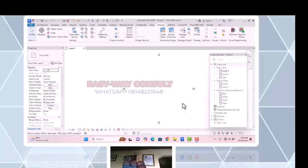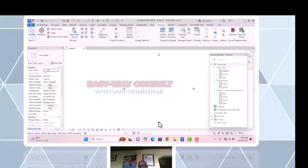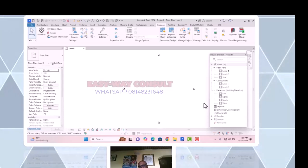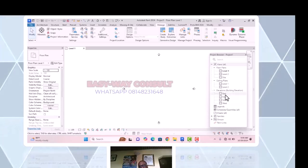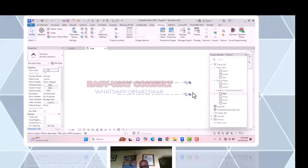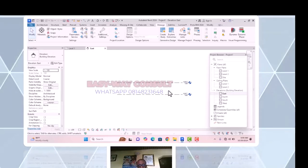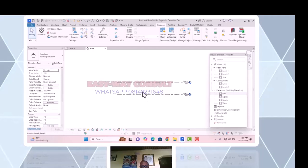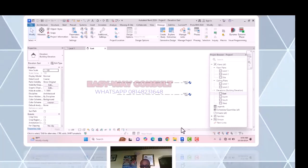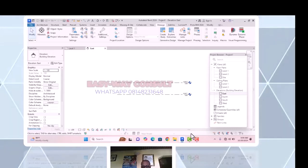So to make your level, you go to any of the elevations, or you can click on this camera, but I would prefer to go to the elevations. If I click on this elevation, it will show me the 2 levels that are there, which I can also change. If I should measure it and I see it is not what I need, I can change it. I can add more, the rest.